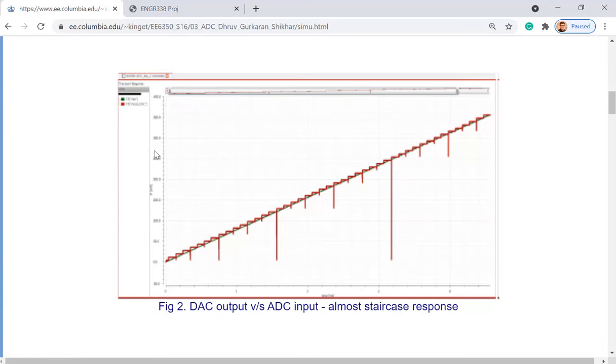so it's a DC sweep. I think in one of the labs at the very beginning of the semester, you did a DC sweep, didn't you? It's a .dc with the voltage source from 0 to 5 and things like that. Just feed that voltage into your ADC and probe the output of the DAC, to show the stairs. And there's one thing you have to do, which I did 10 years ago and forgot how to do. All the data points are being plotted in LTspice, right? So there should be a way to extract the raw data and plot it in MATLAB so you can process it. Otherwise, it just shows up in LTspice.